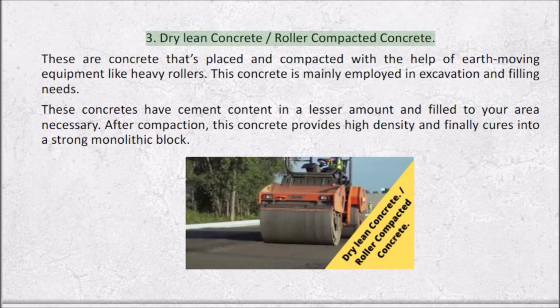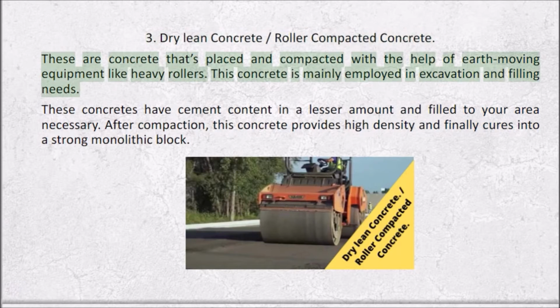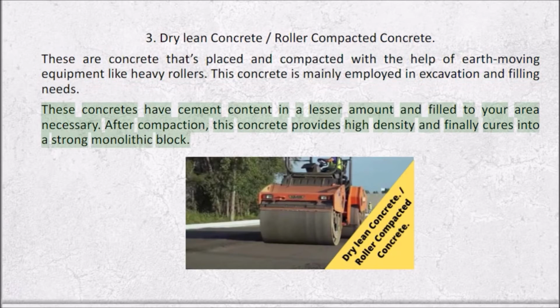3. Dry lean concrete, roller compacted concrete. These are concrete that's placed and compacted with the help of earth-moving equipment like heavy rollers. This concrete is mainly employed in excavation and filling needs. These concretes have cement content in a lesser amount and filled to the area necessary. After compaction, this concrete provides high density and finally cures into a strong monolithic block.